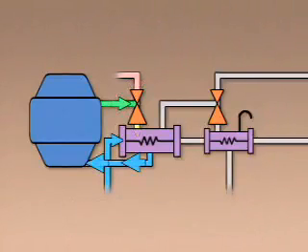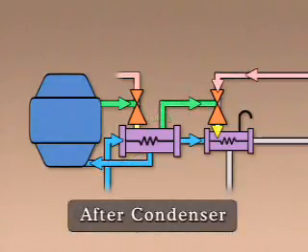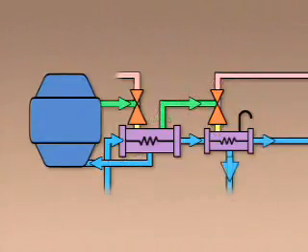There, the steam condenses and drains back to the main condenser, while the air flows into the second-stage air ejector. The steam-air mixture that leaves the second-stage ejector flows into the shell of a second condenser called an after condenser. There, the steam is again condensed and routed to a drain tank or back to the main condenser. The air is vented to the atmosphere.